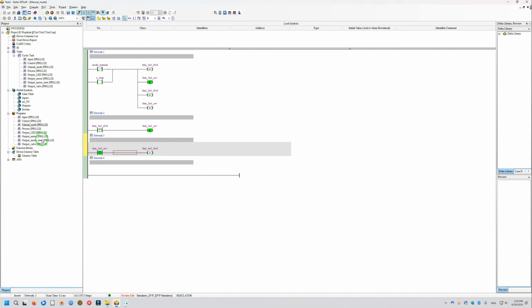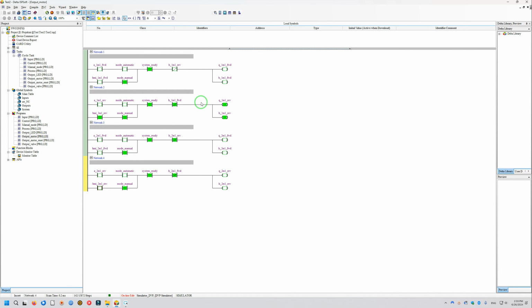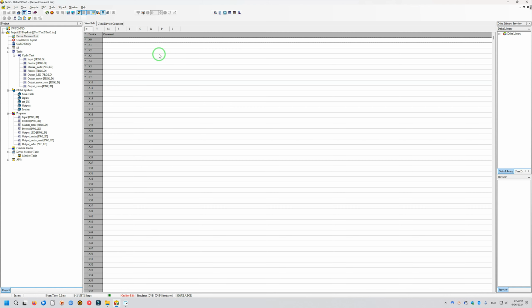Maybe, just maybe. There is another thing. I want to add some limits. For example, I cannot run the motor immediately after running forward. I can jump to reverse immediately. Maybe we have contactors here, so the motor decelerates a little bit. We need a small pause, for example. So let's check our timers. Let's begin with T10, for example.